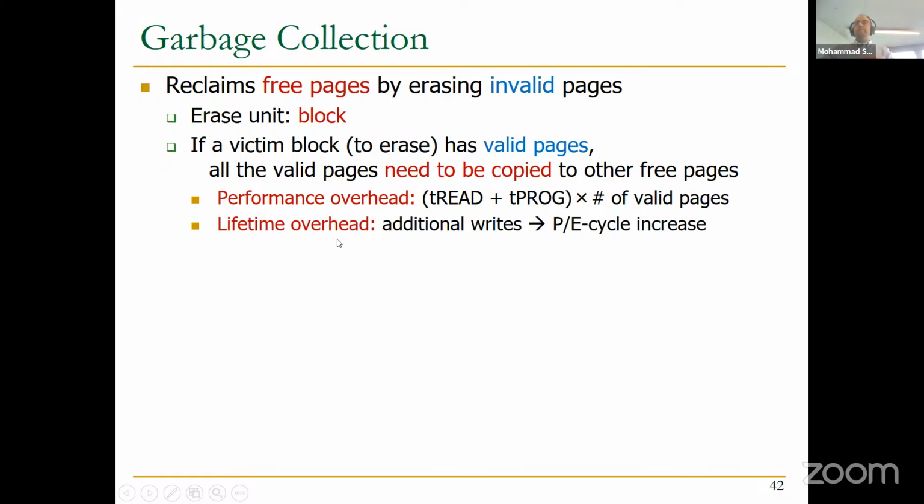It also has lifetime overhead, because now you have additional writes because of this copying, and that increases the program-erase cycles. This is also called write amplification: the number of writes sent from the host is one number, but the number of writes you actually have in your SSD is usually much higher. One of the reasons is this internal copying inside the SSD for garbage collection.